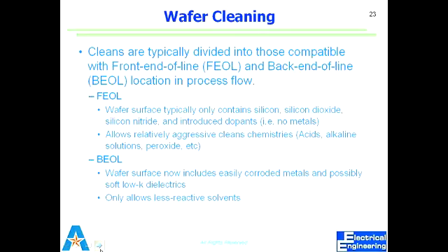What we do is we dip maybe one wafer and tweezers in a beaker filled with acetone. Leave it there for 10 minutes. It's going to remove everything. Nail polish remover has a very small concentration of acetone. That's why it can be used. But acetone is not a good solution. We don't want to inhale it. So the first step is we put it in a beaker inside the solvent hood. Leave it there for 10 minutes.